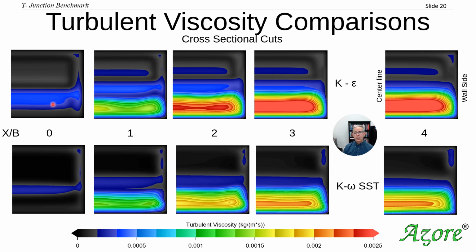You'll see here that we know that the turbulent viscosity is low at the beginning because we have all those screens and everything that we controlled the turbulent structures in our fixture to make sure that they're low. And so you can see right here, this is where the two gas streams are meeting, and so our turbulence is beginning to form. Our turbulent flow structure is right where they begin. So here is the shear layers between these two gas streams when they meet right here. The top it's low, the bottom is low, but then it's higher right here.